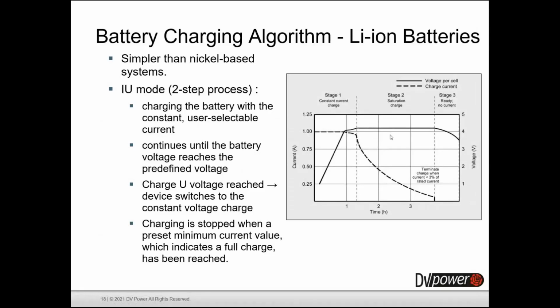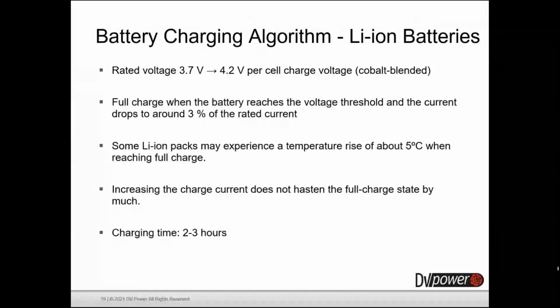Only lithium-based batteries cannot be used immediately after charge. So they need to be left for a certain amount of time with no current, just for all the cells in the pack to reach optimum level. Rated voltage. This boost voltage for a lithium-based battery is somewhere around 4.2 volts per cell.